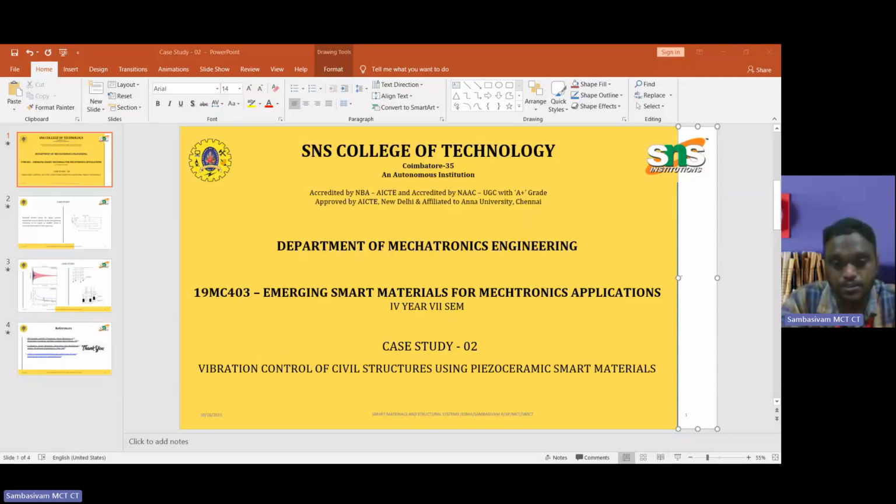Piezoelectric refers to substances that have the following unique property: an electric charge is produced when a piezoelectric substance is subjected to a strain, which is the direct effect. Conversely, a mechanical deformation also occurs when an electric field is applied, which is said to be the converse effect. The direct piezoelectric effect is used in devices such as microphones, accelerometers, and ultrasound transducers. The converse effect is also used in actuators such as ultrasonic welders or ultrasonic motors.